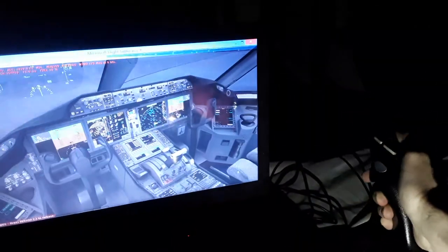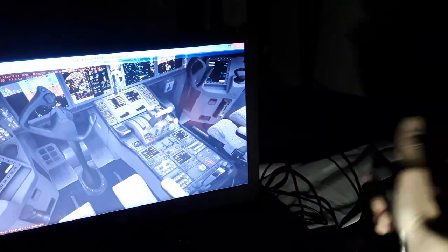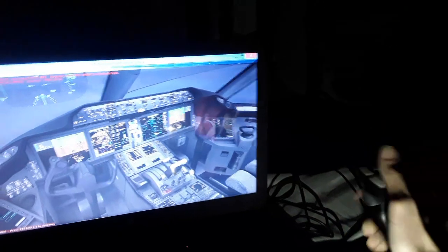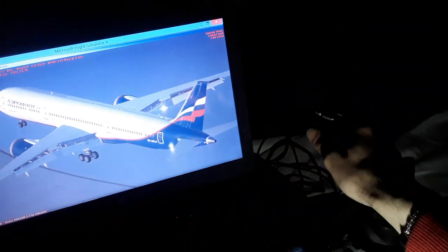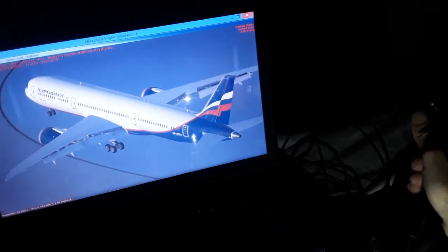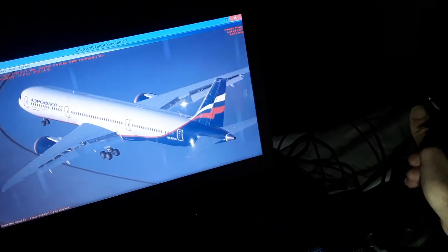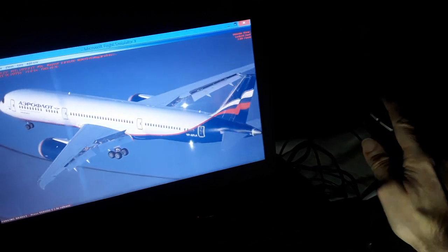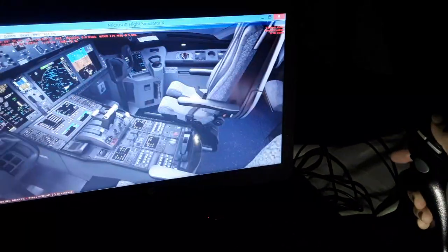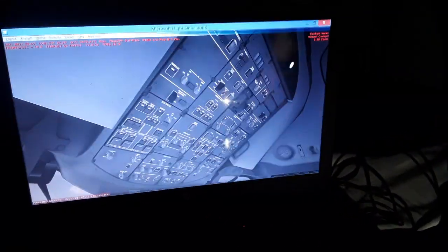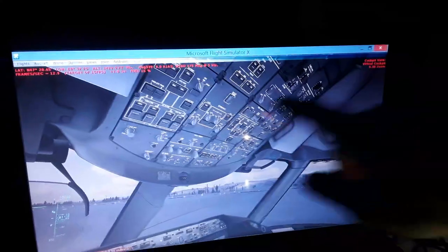So you can see here when we move the flight controls up and down, the rudder pedals. All the flight controls using the wings, like the rudder, the elevator, the horizontal stabilizer, ailerons and spoilers, all need hydraulic power from the engines. And we pressurize some of this hydraulic fluid to increase the hydraulic pressure. We also have hydraulic pumps, engine driven and electrically driven.